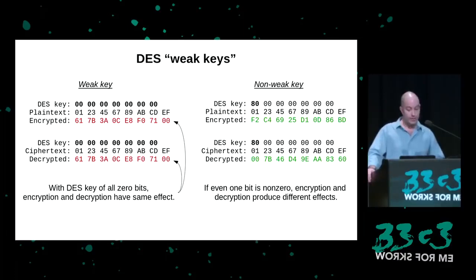When tested with the descrambler in custom mode, the weak key behavior changes. Using a key of all 0 or all 1 didn't produce the same results in encrypt and decrypt modes. Looking at the other hardware register, testing the DES peripheral with different values in the 8-bit register and using weak keys shows that the standard DES weak key behavior still exists. So my hunch at this point is that one customization affects the key and the other customization affects the data. At this point, I can't be certain, but I have a good feeling about the theory, so I continue to investigate.